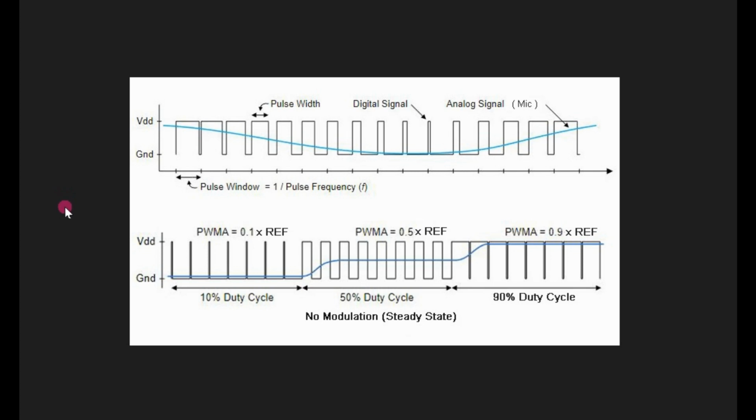Finally, let's look at the duty cycle, or mark space ratio. That's an old-fashioned term. You're used to this now. You can see how varying the voltage changes the pulse duration. But where do we want to set the PWM duty cycle at rest? In other words, when you're not speaking into the microphone, what is the duty cycle of the PWM? And the answer is 50%.